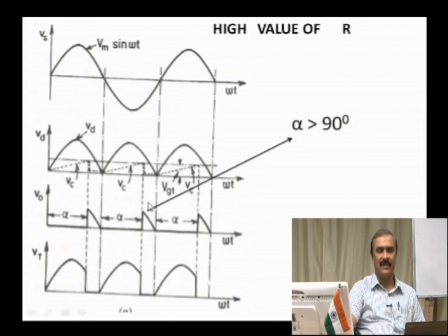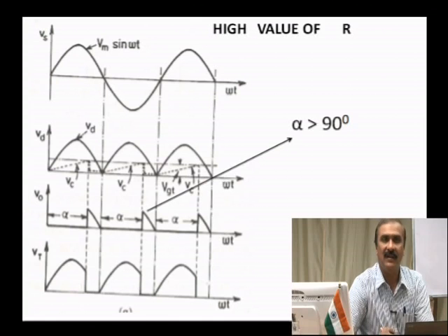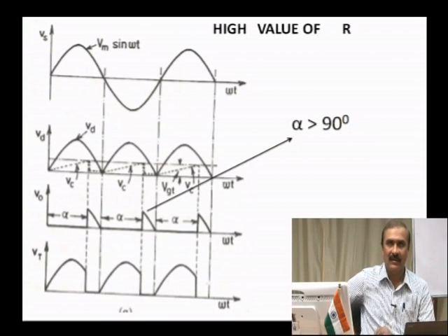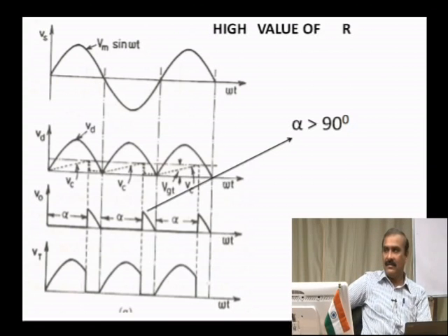Now, this is all about resistance and resistance capacitance triggering circuits. So, this is a very important concept to understand resistance firing and RC firing. So, in case of resistance firing, you have seen that the maximum triggering angle is 90 degree, and voltage and current are in phase in the circuit. Whereas, in an RC circuit, you can obtain firing of SCR